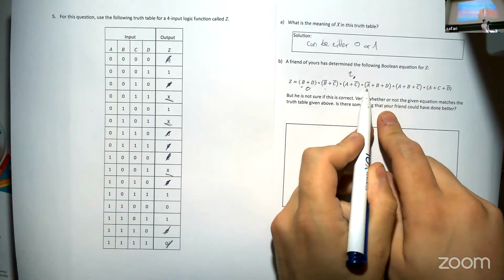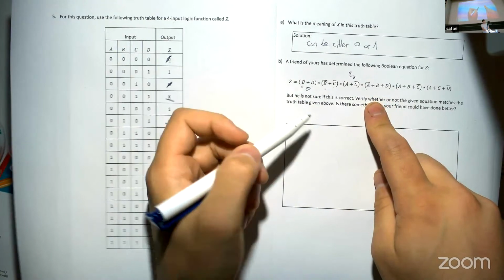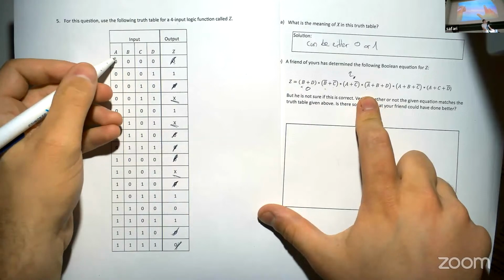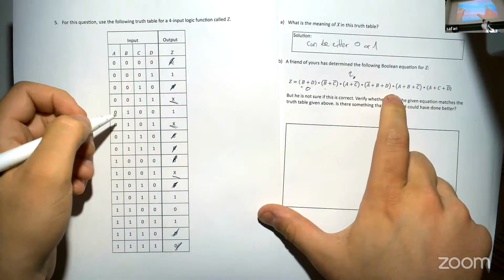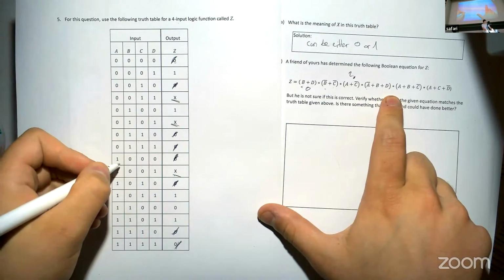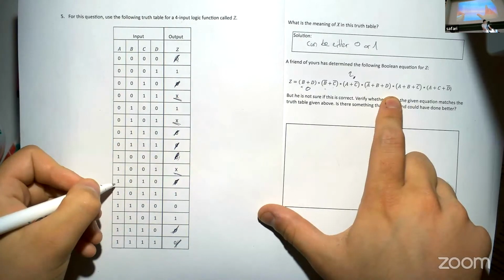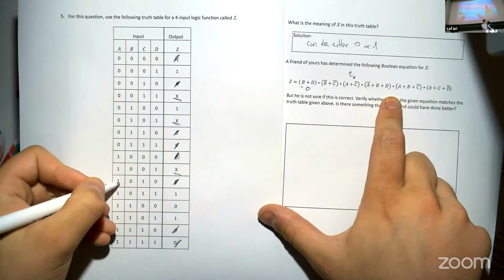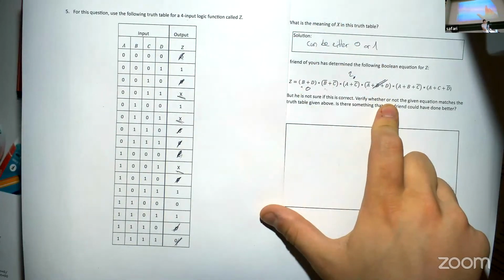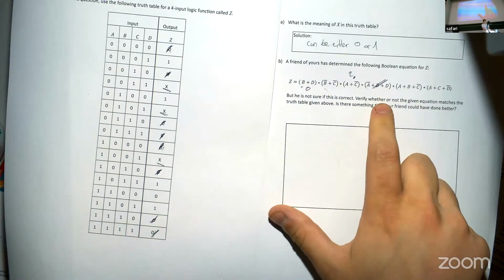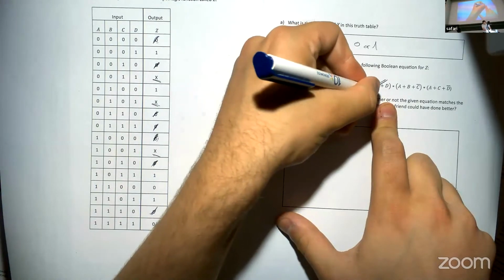Okay, then we have not A, B, or D. So you go through here and you look for cases where you have A, B 1, B and D be 0. So let's see down here. So this case is already covered, and this case is also already covered. So this one's definitely unnecessary, which makes sense because the first equation covers this one. So this is just redundant.